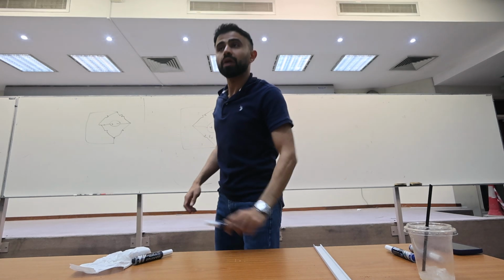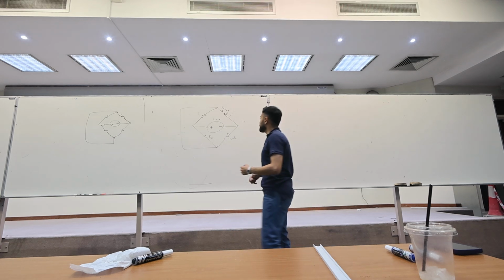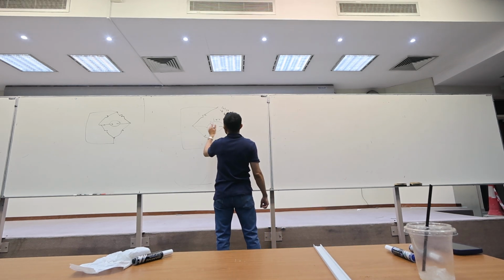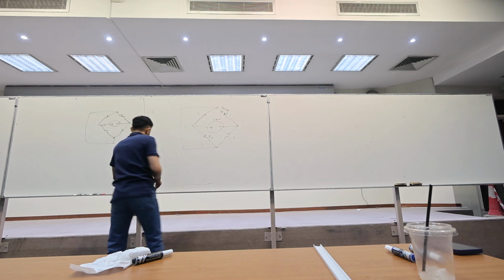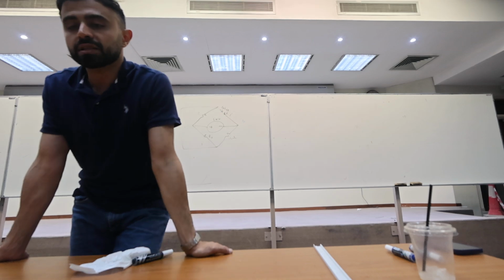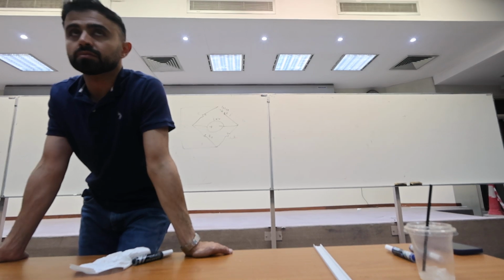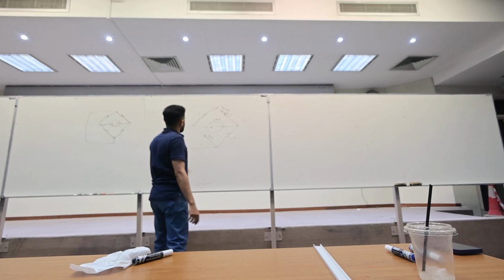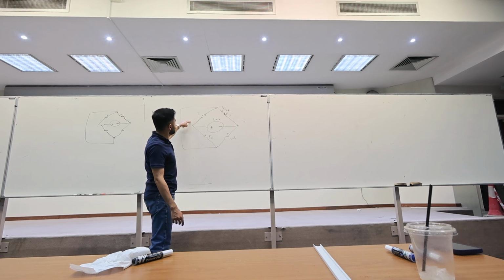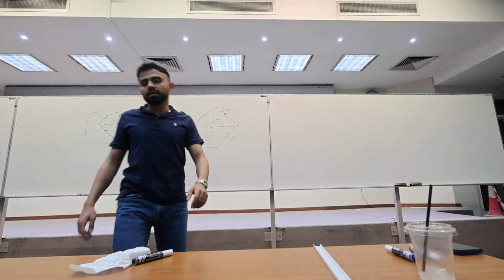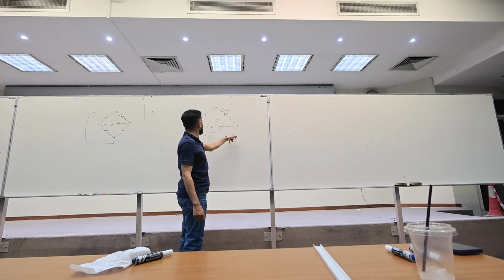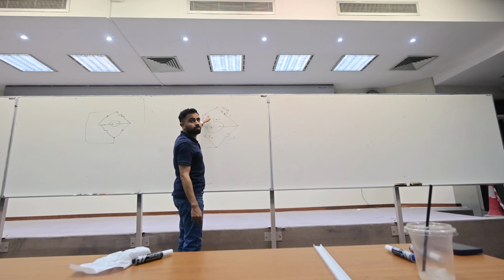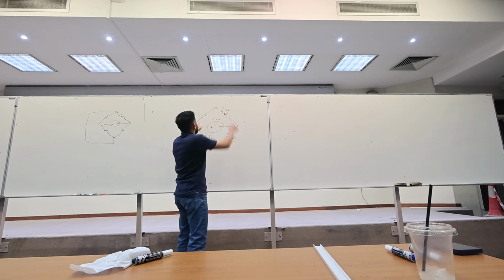How to solve this example? Well, you can do it with basic KCL, KVL. So what is the question? Consider the circuit. Which elements are in series? Any elements in series? No. Which elements are in parallel? Clearly, the 6 ohm resistor is in parallel with the 4 ohm, and the Rx is in parallel with the 2, because they have the same node.